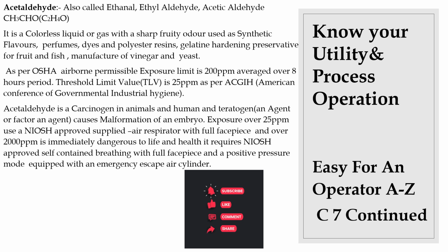For exposure over 25 ppm, you have to use a NIOSH approved supplied air respirator with a full face piece, and over 2000 ppm is immediately dangerous to life and health. So it requires NIOSH approved self-contained breathing apparatus with a full face piece and a positive pressure mode, equipped with an emergency escape air cylinder.